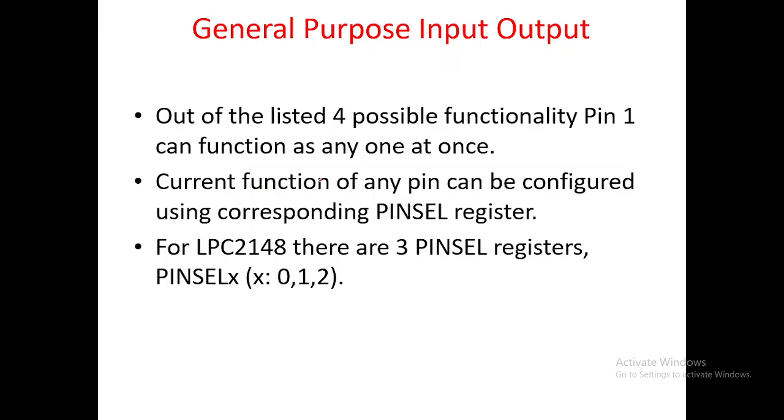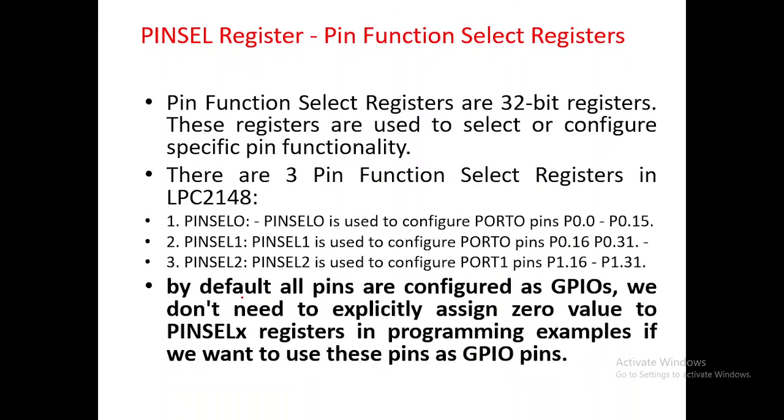Then the current function of any pin can be configured using the corresponding pin select register. The LPC2148 has 3 pin select registers: 0, 1 and 2. The value of the pin select register decides the function of that pin. Pin function select registers are 32-bit registers. These registers are used to select or configure specific pin functionality.